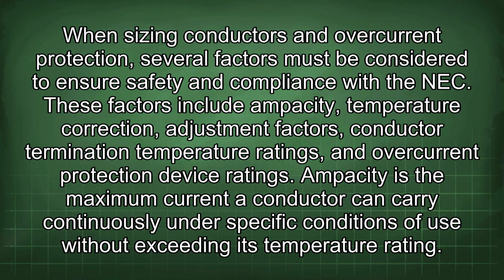When sizing conductors and overcurrent protection, several factors must be considered to ensure safety in compliance with the NEC. These factors include ampacity, temperature correction adjustment factors, conductor termination temperature ratings, and overcurrent protection device ratings. Ampacity is the maximum current a conductor can carry continuously under specific conditions of use without exceeding its temperature rating.